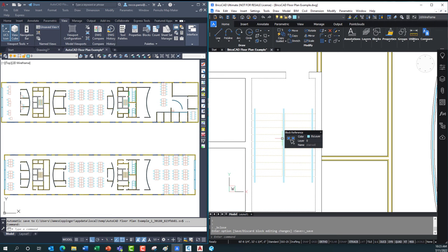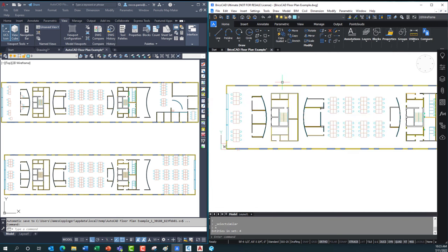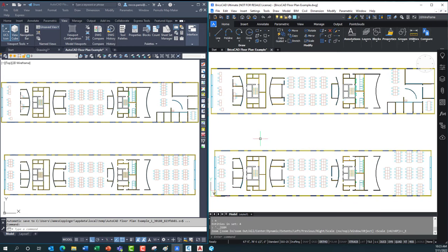And if you don't want it as a block when you're done, it's not a problem. I just come back here and select similar and use the explode command. Now everything's back to basic graphic line work, if that's what you need. The blockify tool gives you that option of finally being able to use block creation and explode on the fly very, very quickly. And it really is the best way I've ever found to be able to do multiple plan updates across multiple areas of your drawing.